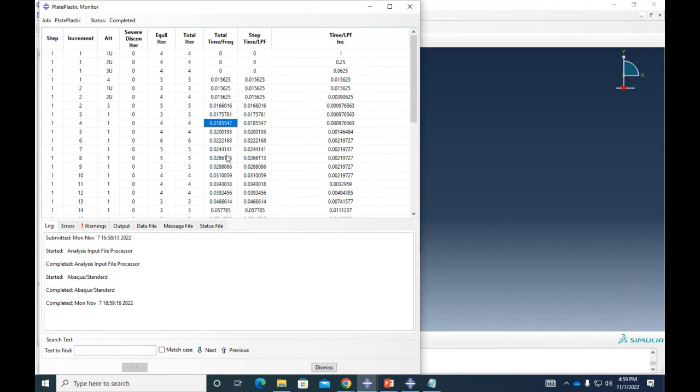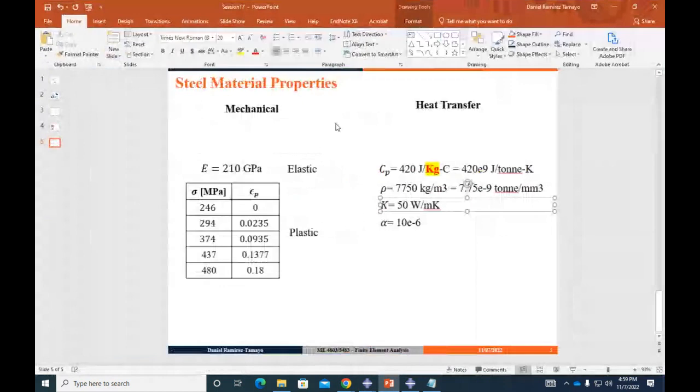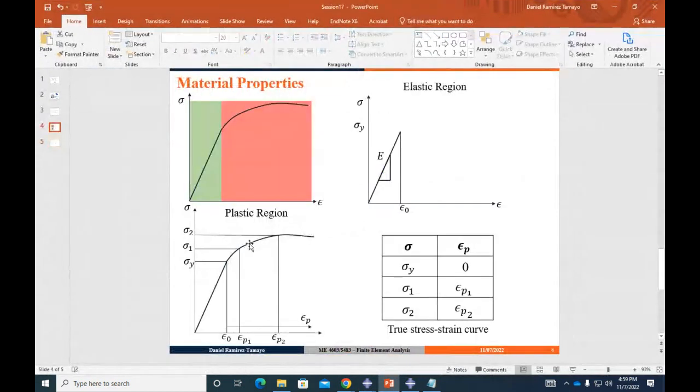All right. As we start yielding, we cannot apply the load like that because we don't have a linear relationship, right? So we have to break it and try to stay within this behavior in here. Because this is a nonlinear behavior, I have to apply that load in a nonlinear way, which is just break it into smaller increments.